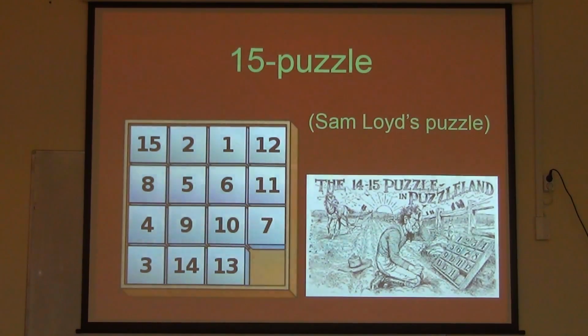So when you use vias, is the problem three-dimensional? When you use the holes to connect layers. Vias, not necessarily, it depends how you define it. In the layer technology, which is, I think, more than 50 years old by now, the vias were always considered as via holes. Yes. But in modern technology, we permit that a via goes just from one layer to the next one, and the same area can be used by different vias later. That's how the technology actually works.